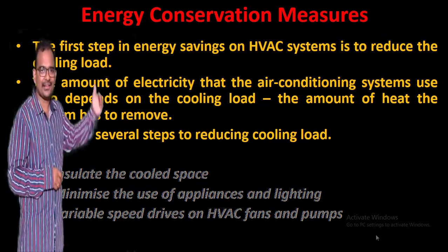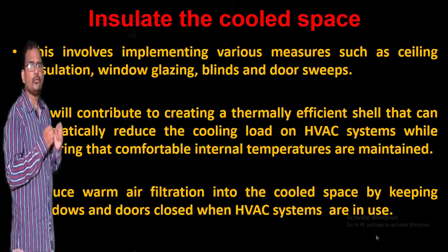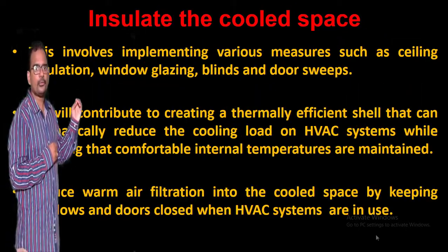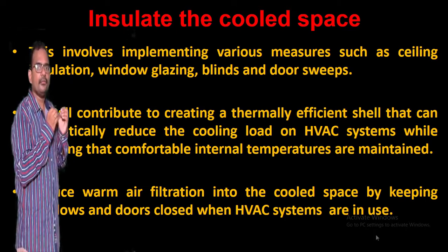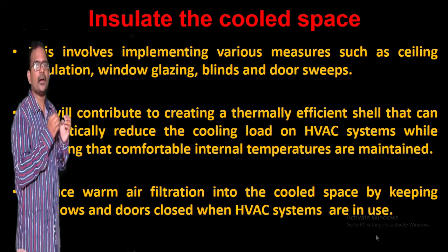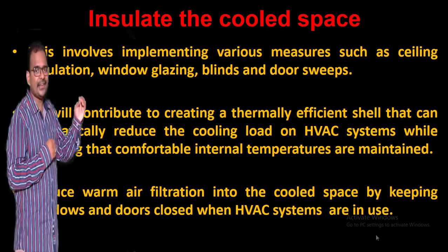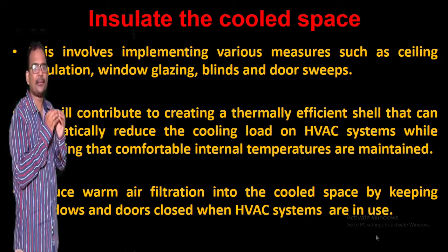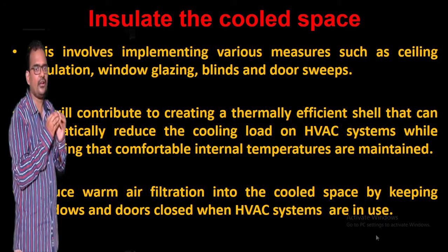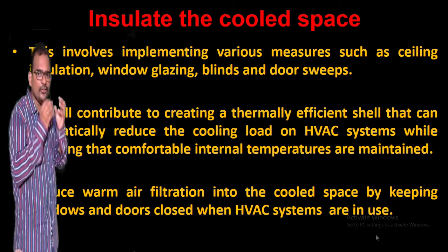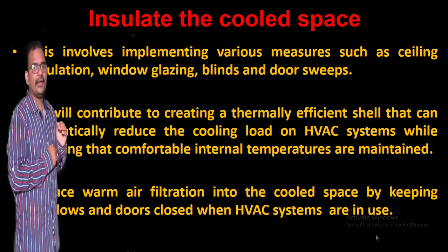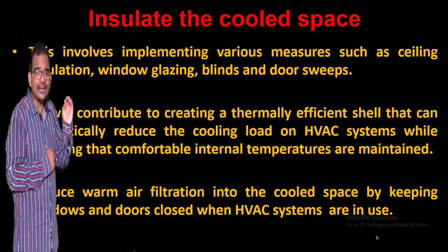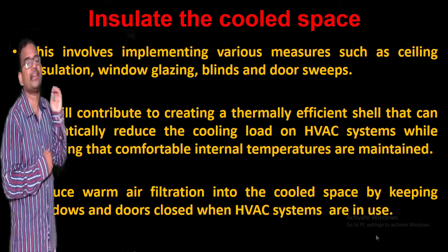Now let's see this one by one. Insulate the cool space. So this involves implementing various measures such as ceiling insulation, window glazing, blinds and door sweeps. And all these things will contribute to creating a thermally efficient shell that can dramatically reduce the cooling load on HVAC systems, while ensuring that comfortable internal temperatures are maintained.